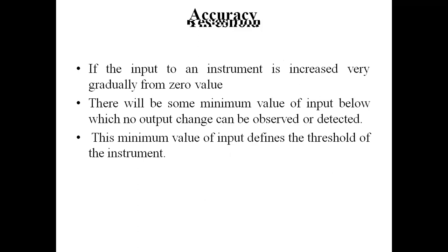The next one is the threshold. If the input to an instrument is increased very gradually from zero value, there will be some minimum value of input below which no output change can be observed or detected. This minimum value of input defines the threshold of the instrument.